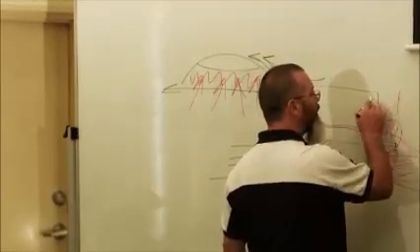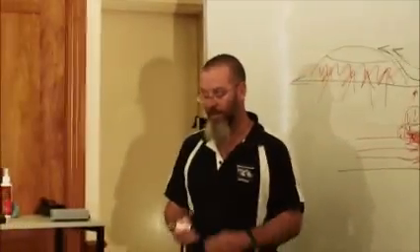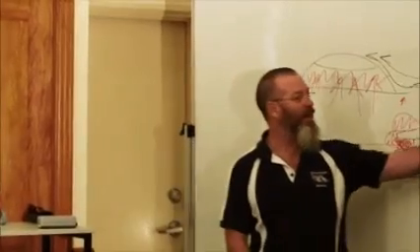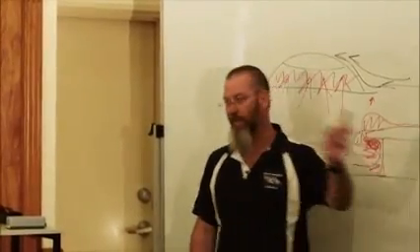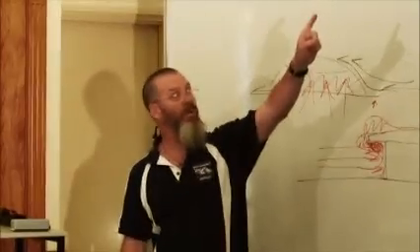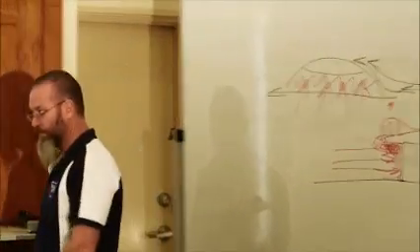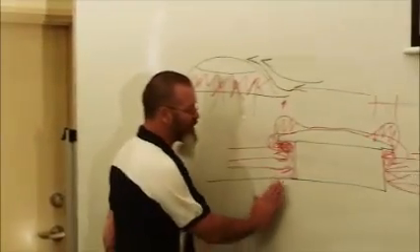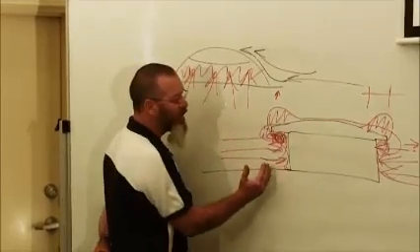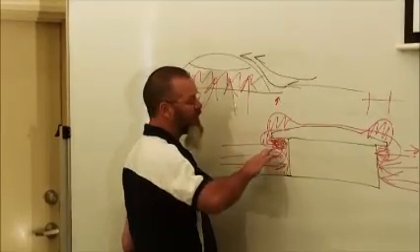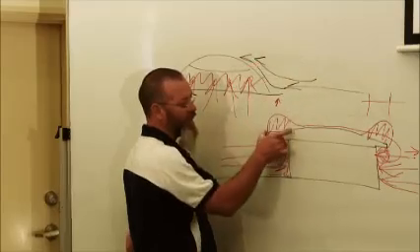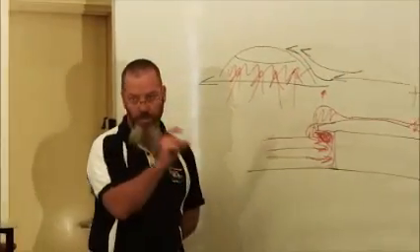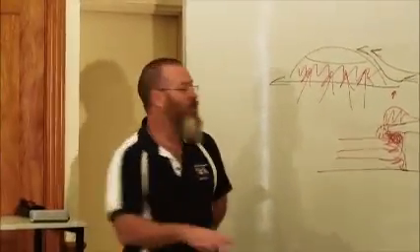And if you think about it, some pointy head, to use the technical term, has actually sat down and calculated this area of high risk as being 1.2 metres in from the edges. Okay? Now, if this was a wrap-over roof or a gable end roof, it's still an edge. If you think about it, the wind comes up. Just pretend this was a gable. The wind comes up, compresses against the building, comes up over the edge like that, and creates this 1.2 metre wide strip of higher pressure, because you've got this large vacuum on the side of the building.